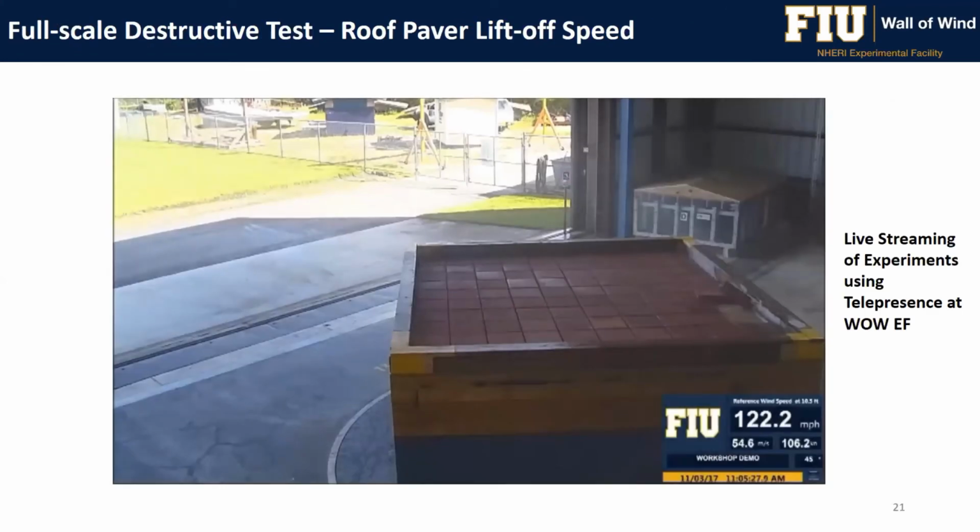And one more example of destructive testing that we have been doing over the past few years is related to pavers. This is at an oblique wind direction, so wind is coming from the right side, approximately 45 degrees. We have generation of what we call conical vortices here. Those vortices create very high suction on the roof, and you can see the damage pattern. It starts slowly to lift off those pavers.